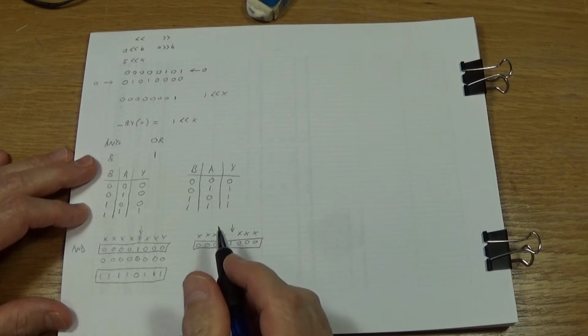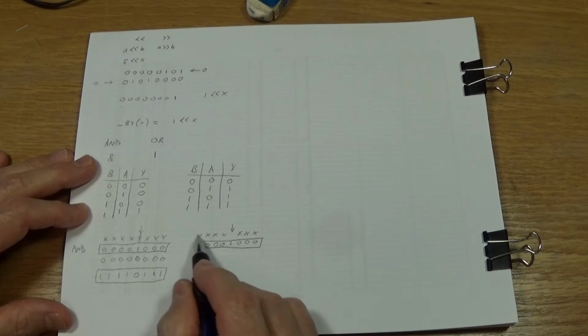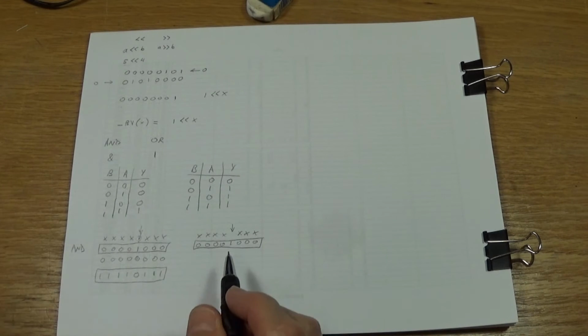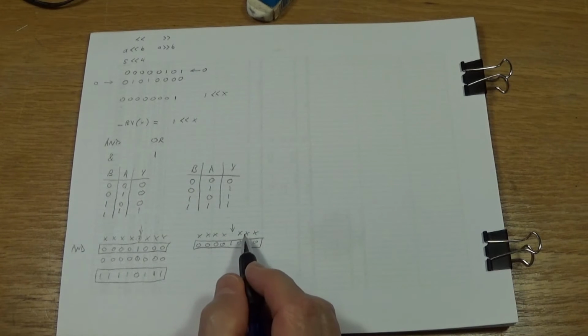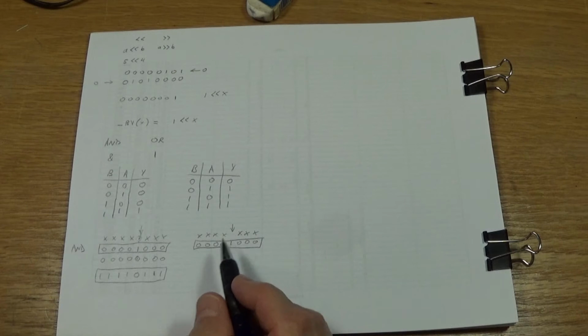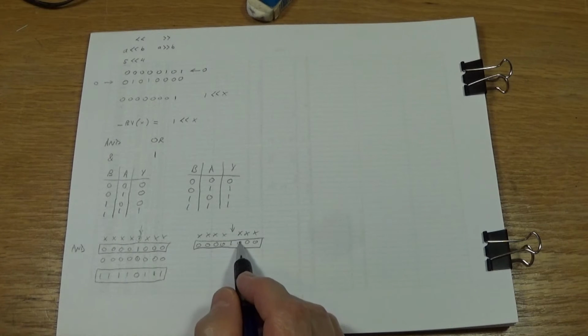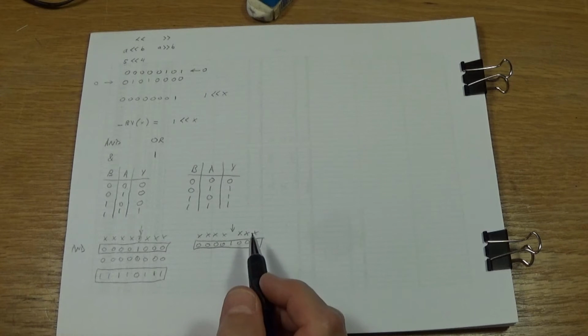And so we read the register, and then we OR it with the mask, which sets this one bit, leaves all the other bits alone, and then we can write it back to that register. That way we've made a change to that particular bit in the register, but we have not affected any of the other bits. And again, same with the AND, we can put numerous 1s in here, and for any one that's a 1, that bit will get set.